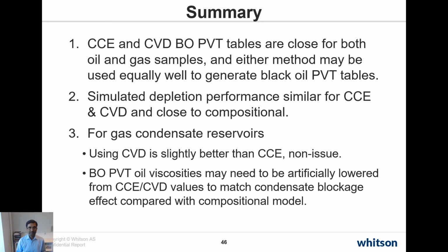For gas condensate reservoirs, CVD is slightly better than CCE at the end of the production period, when oil and gas production rate was quite low, and this is not an issue. In case of gas condensate reservoirs, if there is a condensate blockage effect, the oil viscosity may need to be artificially lowered in the black oil PVT table if we want to match the black oil with compositional model performance.